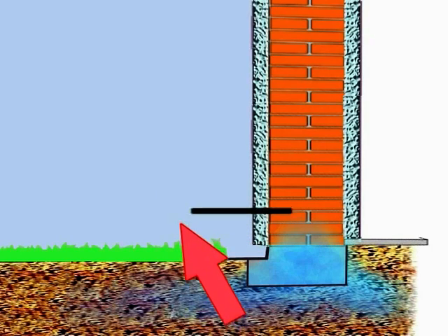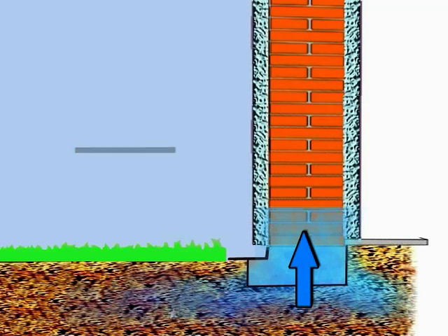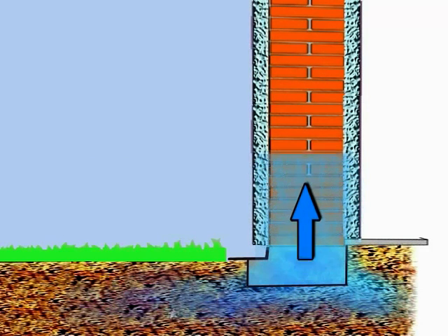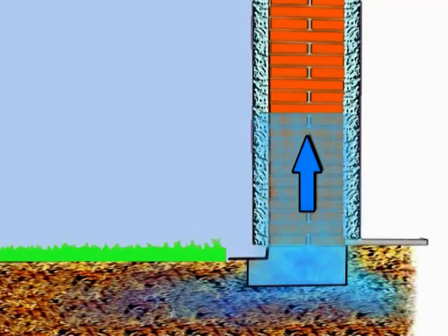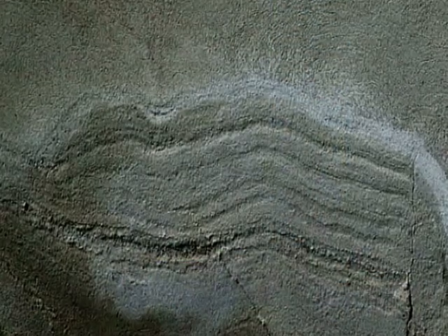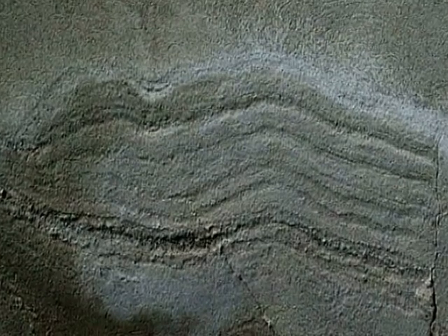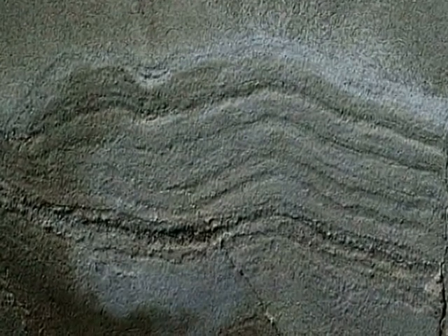In old masonry that lacks a horizontal moisture barrier, or where it is partly rotten, ground moisture rises into the masonry. Ground moisture in the capillaries of masonry rises to a point where it oozes out as water vapor at the so-called evaporation zone. This results in the capillary head in masonry, which grows a little every year. It may be manifested as annual rings caused by different degrees of salt efflorescence.